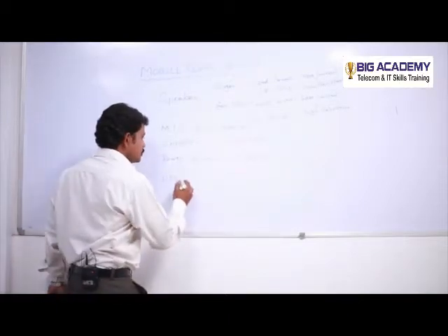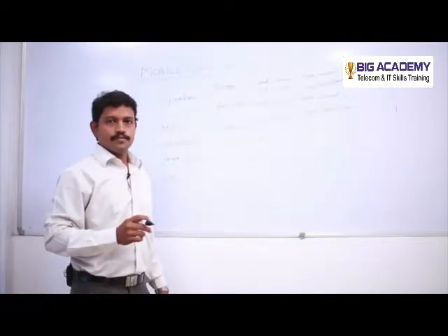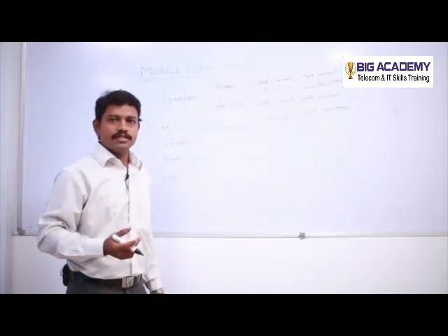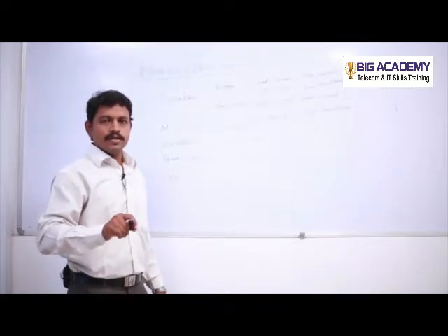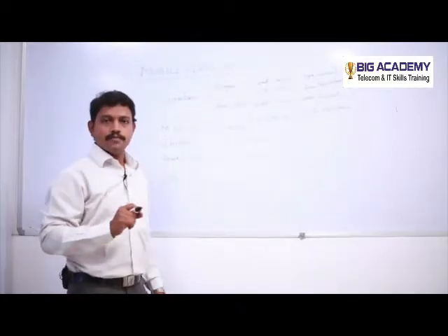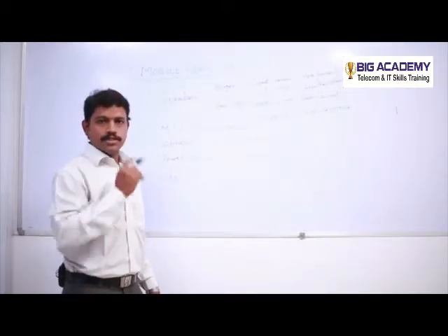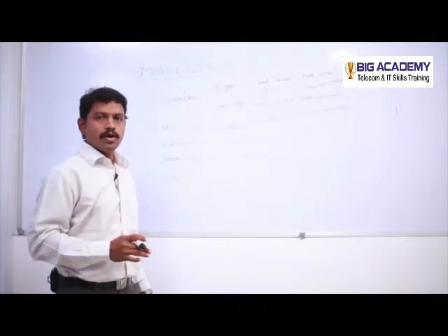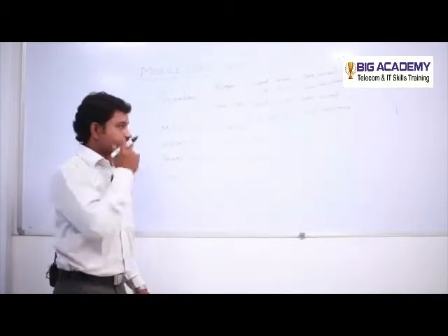So this should be measured before you change. If a customer asks, I can't hear the voice, you can't directly change the mic or the speaker. You have to check. As an engineer, we have to check whether the speaker has the exact value within the range. Then we can diagnose, do the changes, troubleshoot it and give the solution to the customer. This is how you have to do the hardware service. You can't directly open it and do the changes.